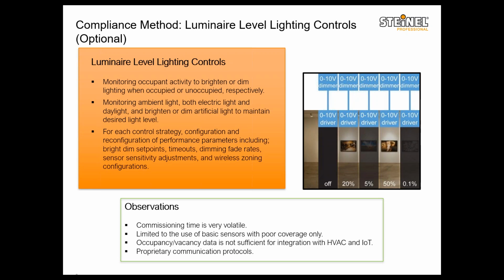Even to my interpretation, the amount of detail that the code has gone into for the occupant sensor control compliance method shows that they have more emphasis on that method rather than using the luminaire level lighting control. So luminaire level lighting controls requires some form of occupancy sensors mounted in each luminaire. Now this fixture mount control should meet the following three requirements.